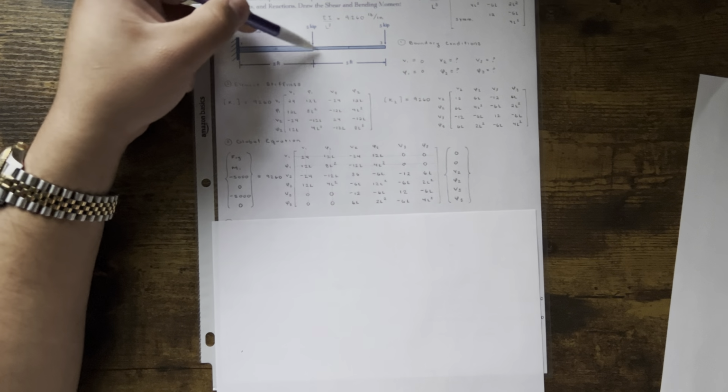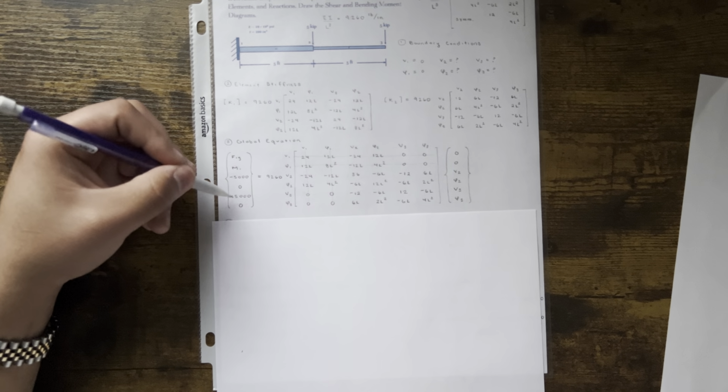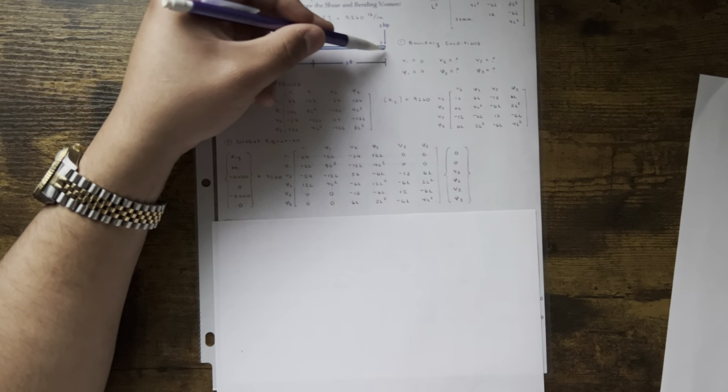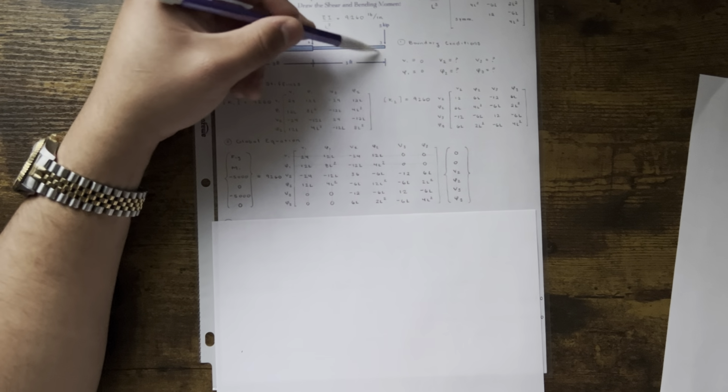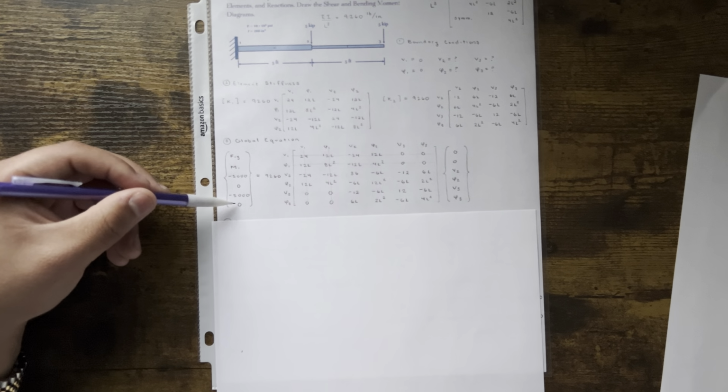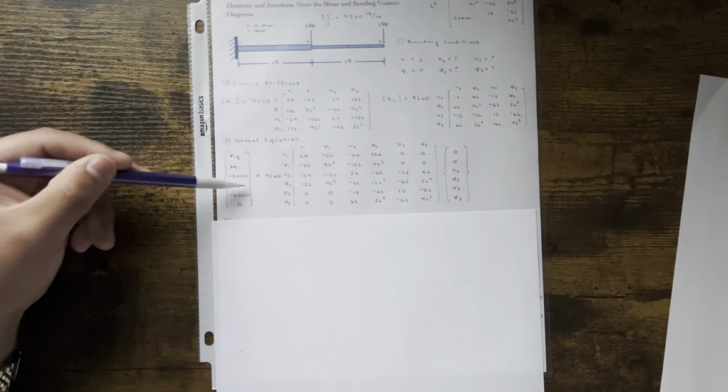Now, just by looking at the actual diagram, you're able to verify that. So you got 5,000 pounds pushing down. So that's a negative 5,000 at node 2. There's 0 moment, right? There's no clockwise or counterclockwise arrow. So that's 0. And then at node 3, you know negative 5,000, right? You see it going down, and you see it right there. 0 moment, it's applied. There's nothing going on at node 3, so that's 0. So just like that, you got these 2, and then these 4.